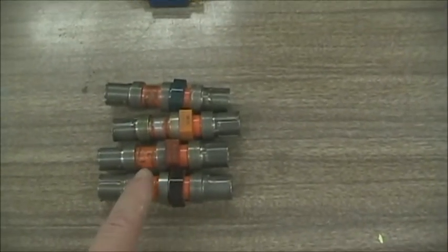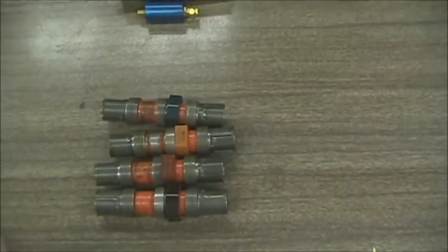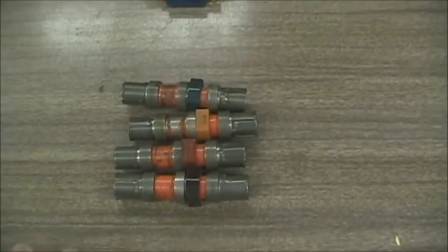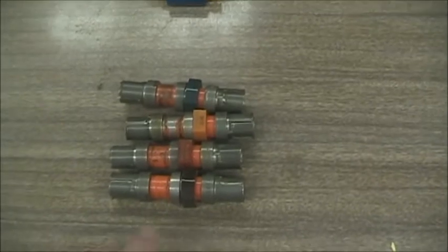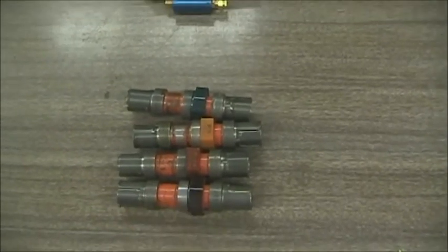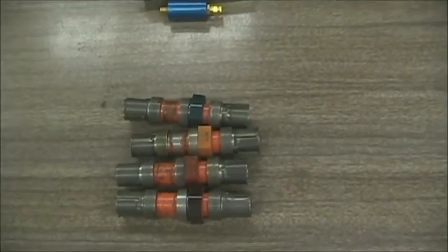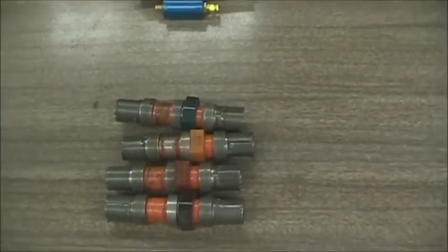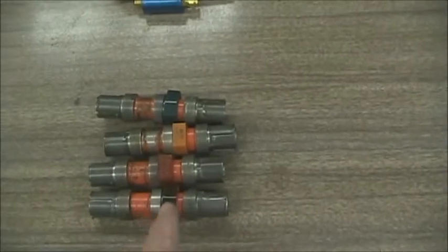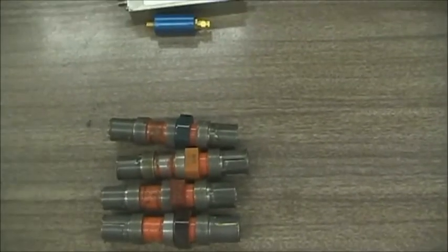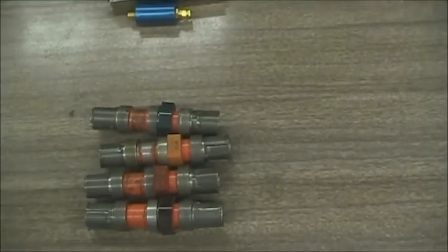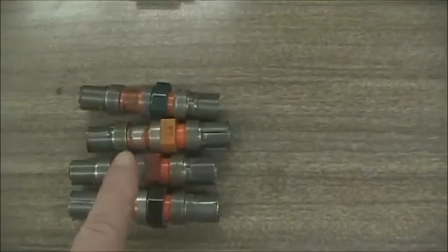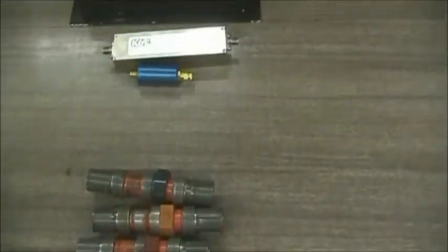That's very useful for us because gain is very difficult to acquire at RF frequencies. So having a calibrated loss can almost allow you to operate with a calibrated gain. Because if we have an amplifier and apply a calibrated loss to it, then we can adjust the power level. So I'll give you data on this.